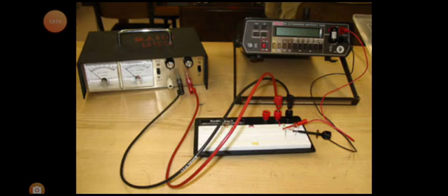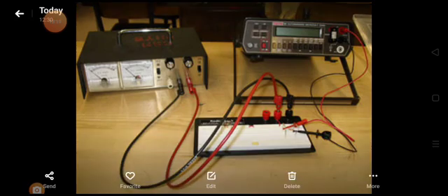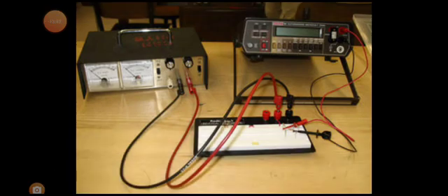But at the same time, one thing was kept into consideration, that this proportionality was valid until all physical conditions were considered to be constant. This means that with passage of time, when temperature of the conductor increases, then this proportionality is no longer valid. This means if temperature remains constant, pressure remains constant, the dimensions of the wire, the physical conditions of the wire remain constant, only up till then this proportionality is valid.